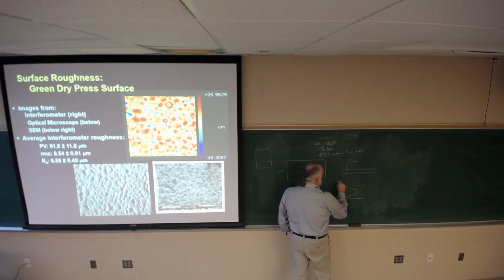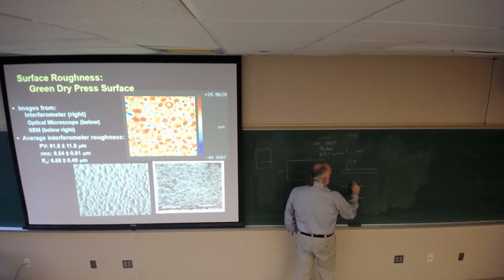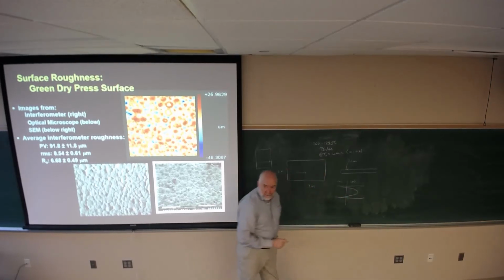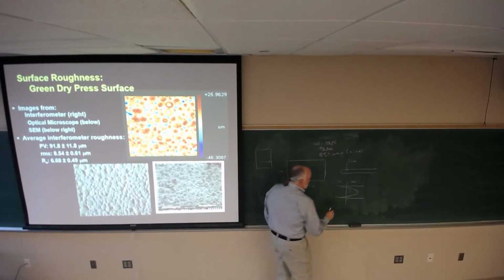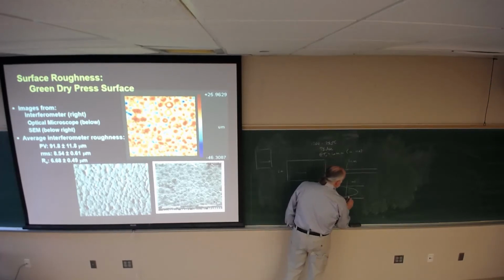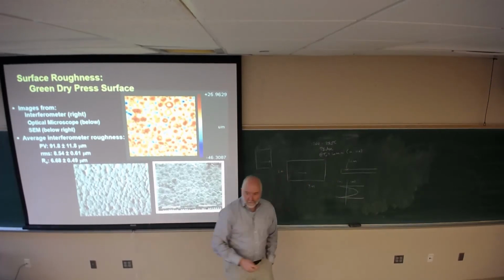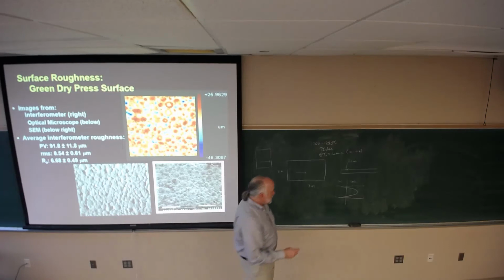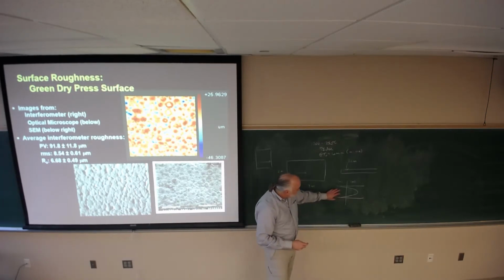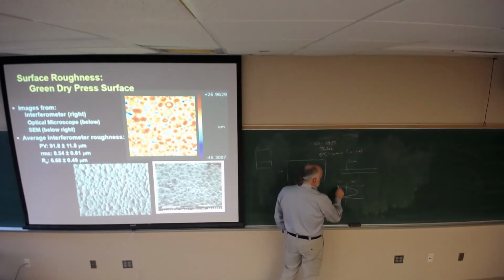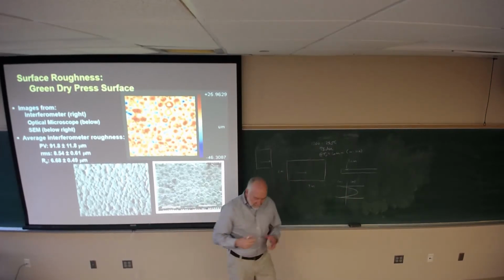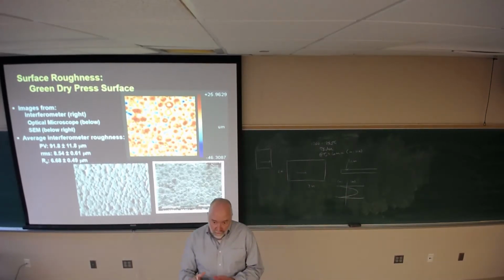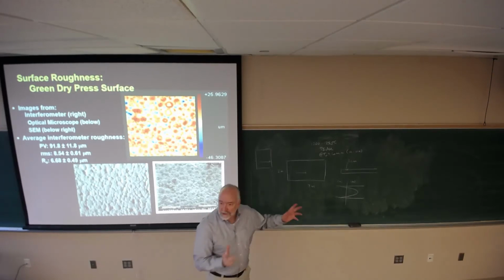So you have compression on this side, tension on this side, and you have a depth associated with that tension or compression. And so you have this surface compressive layer, so you have tempered glass. And the tempered glass idea is, if you get a nick that goes sufficiently deep into this region, and that nick gets into the tensile region, then the piece shatters, right?